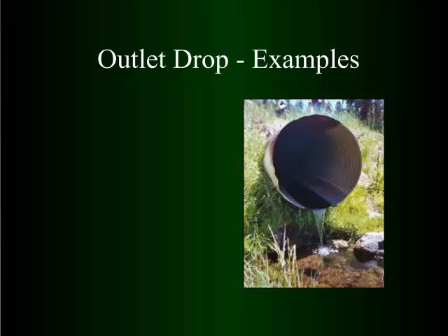The other thing to assess is the drop. If you have a fish-bearing stream, most people like to keep the plunge at 6 inches or under for small fish. This one here, I'm not sure the exact size of the pipe, but you can see from the outflow, it doesn't look like there's any erosion much here. So whatever energy, that height there, it's not cutting. So if it's not a fish issue, it's not a maintenance issue.